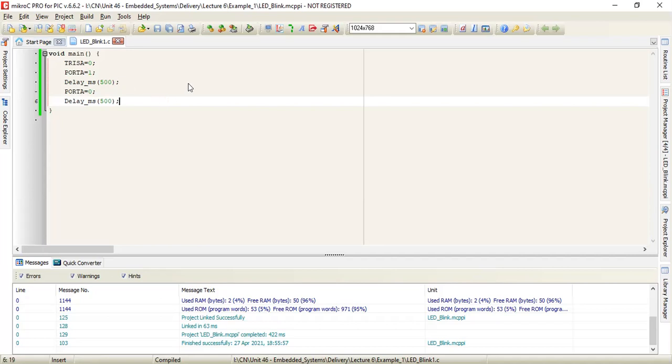For this one, connect an LED to the RA0 pin, and then ground it through a resistor. Then put that hex file into that. Then can you try to run that program, and see what is happening?